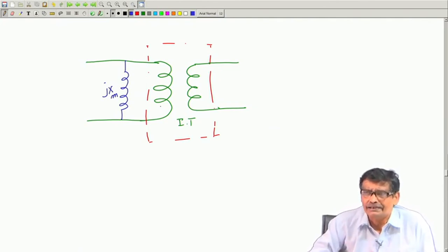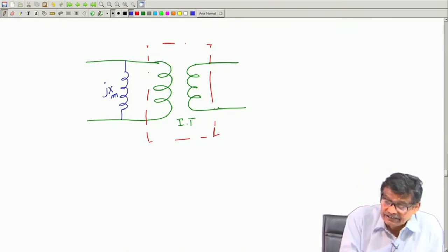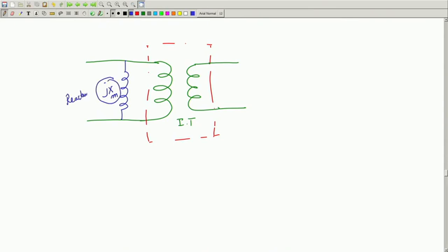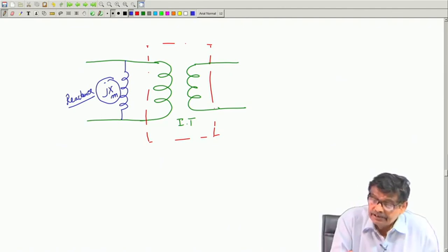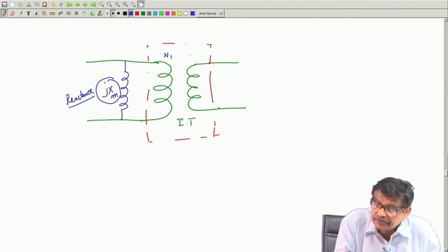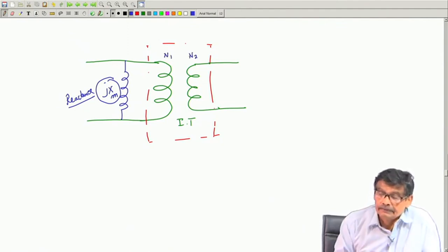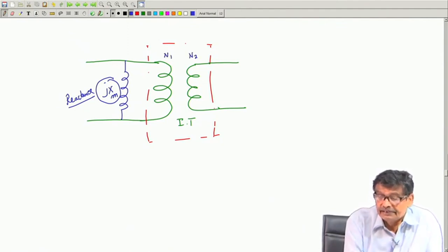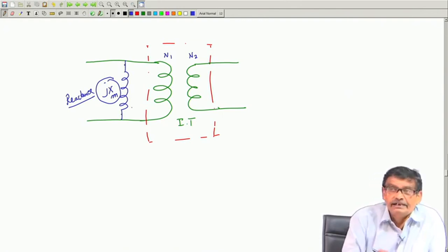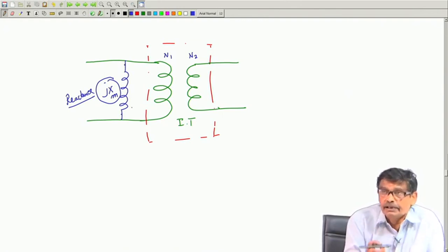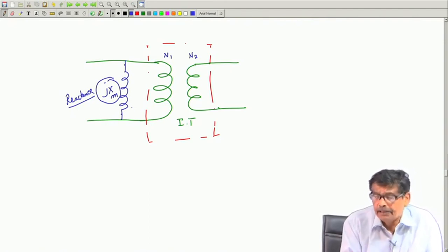Still, it does not have any resistance, leakage flux, or core loss. So, this is a reactance added by me to an ideal transformer, which I have shown in a box, with the same turns ratio N1 is to N2. So, jX_M is external to this ideal transformer and it is not a winding, I am emphasizing this. This is the primary coil.